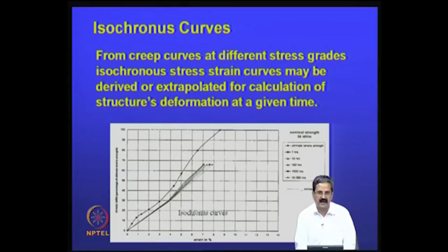So for example, if you would like to construct for 30 years or 40 years, you need to know how much degradation, or strength reduction, there is from the immediate condition to the long term condition. We measure this and get this information from this curve. Different materials have different properties like this, and you can use this as a basis for correcting your tensile strength in the design, which we will see.